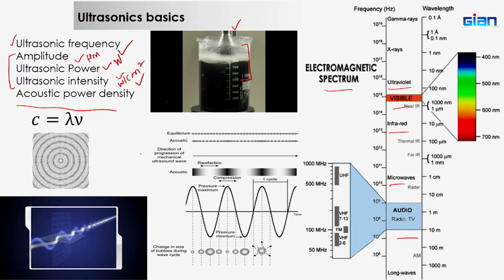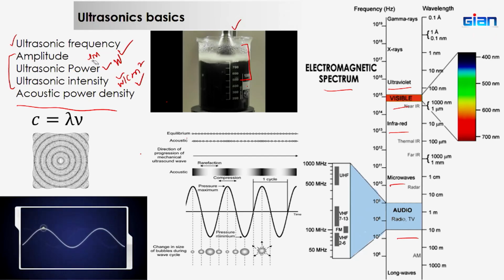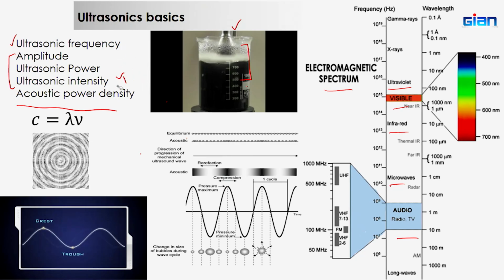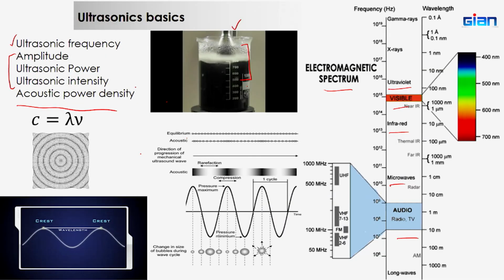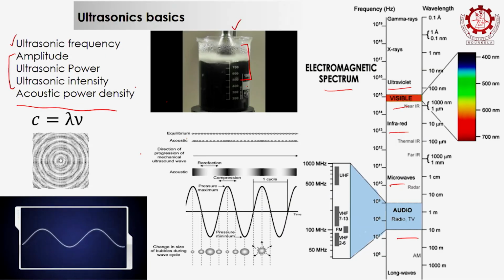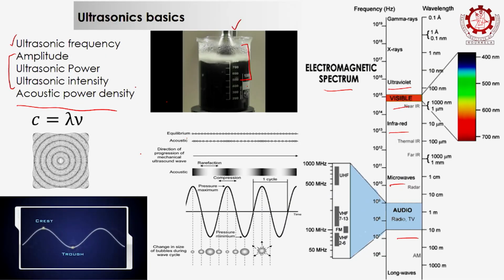I will come back to how we measure ultrasonic power. Another thing related to this ultrasonic system: if you did your experiment for 100 ml of water and now you want to use the same condition for 200 ml, it won't work, because the acoustic energy density distribution changes. That is one of the limiting factors when it comes to scale up.